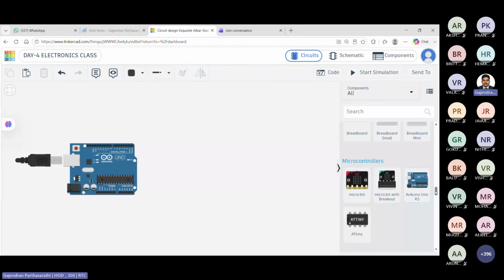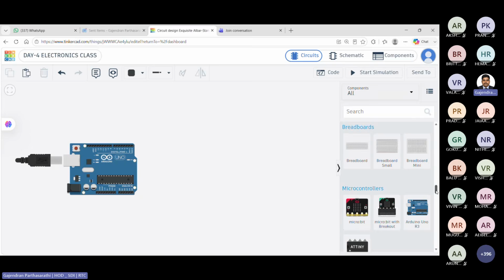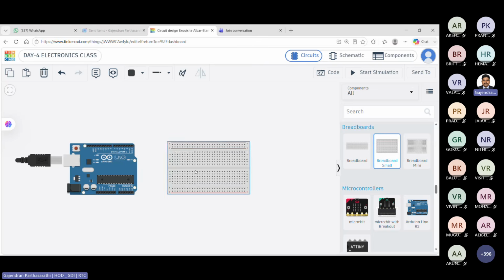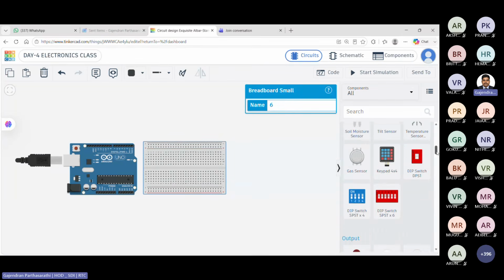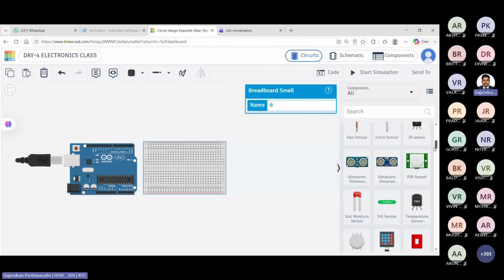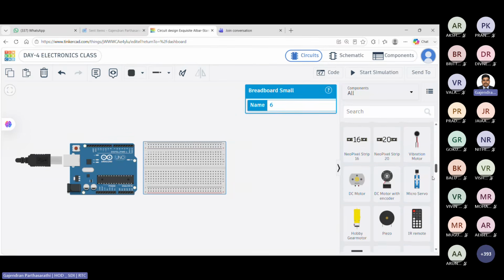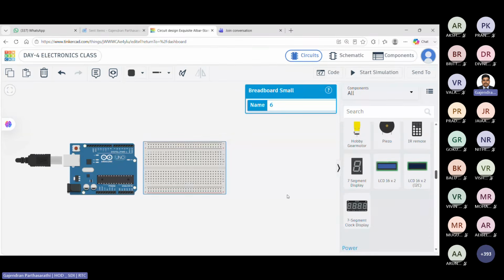Simple experiment. Use the same blinking code to make your buzzer sound. A piezo buzzer is available. Take the buzzer, make use of any one digital input output pin, and connect it with your Arduino.